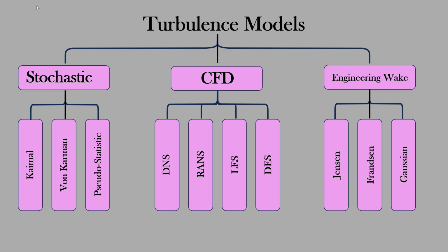So under CFD, you have the direct numerical solution. After that, you have the Reynolds averaged Navier-Stokes. Then you have the large eddy simulation. After this, you then have the DES, which is a combination of a solution of the shortcomings or the cons of RANS and the cons of LES.